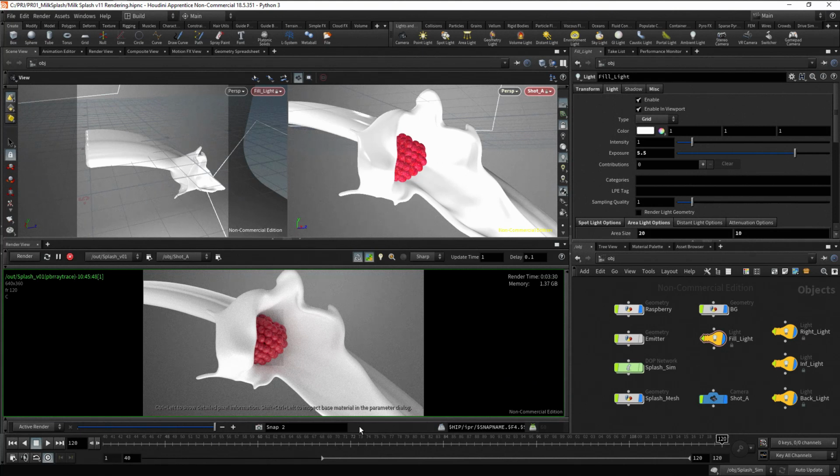OK, the render is finished. Save a snapshot. If we compare it with the previous image, the illumination is better, but maybe the intensity needs to be decreased a little bit. Besides, we have a strange rectangular shadow at the center of the image. Let's disable the Preview button to check if it's only an artifact. OK, the strange rectangular shadow is gone.